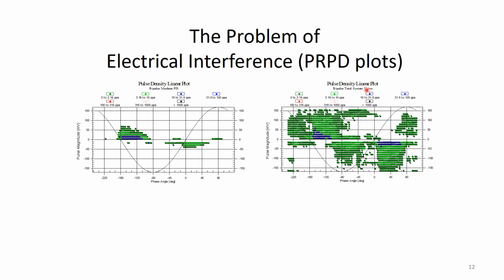If you have appropriate techniques, and there are lots of them out there, you can separate out the noise. In the past, and in fact in many of the systems still used by many of the OEM service providers, those two graphs are combined. But if you have ways of digitally separating stator PD pulses from the noise, you can isolate one from the other.